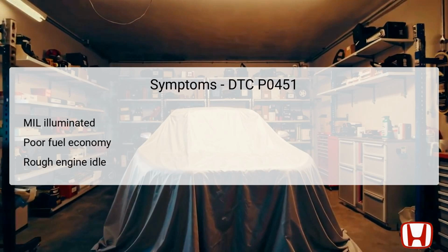A vehicle exhibiting DTC P0451 may show several noticeable symptoms primarily related to the functioning of the FTP sensor and the overall emission system. The most immediate symptom is the illumination of the malfunction indicator light, MIL, alerting the driver of a potential issue.